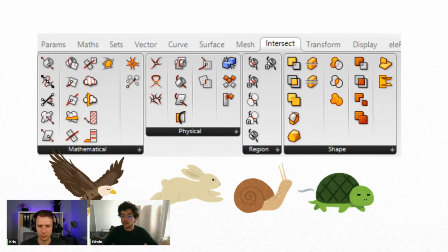And it becomes very complex when you may need to use C# or Python, because there you have the Rhino Common, and the Rhino Common has everything you see in the canvas. All of these components are functions in Rhino Common that you can use in a more clever way. So then I start to use other methods inside C#, because it becomes so intricate to do it with just Grasshopper components that it's better to go directly into C#.